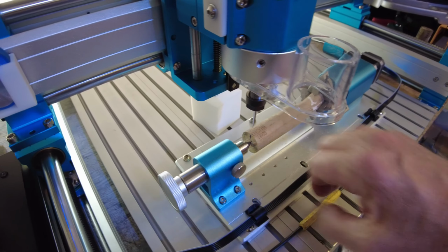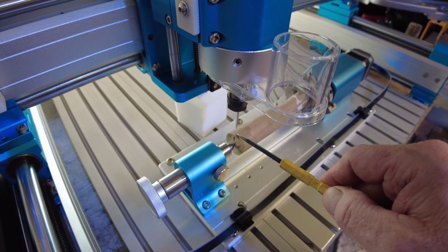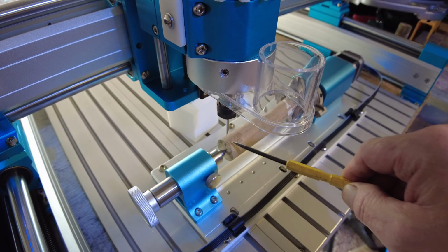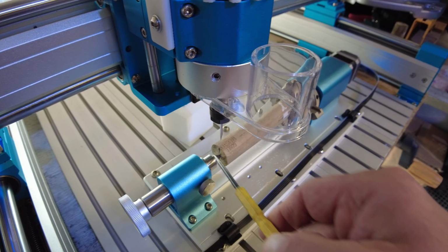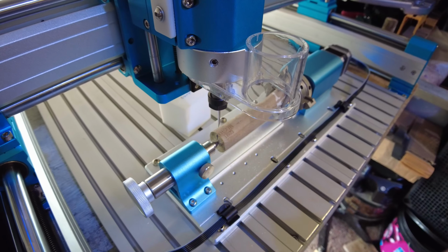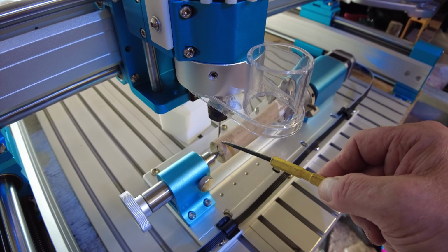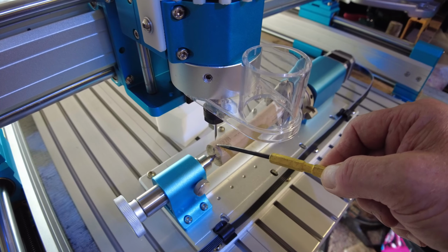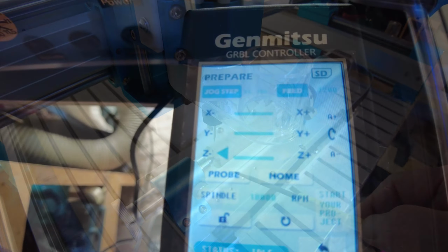Now obviously I've set it in about 5mm from the edge, roughly. But in the software program, you've got to remember that the software unwraps this. So whatever that distance is from there right the way around the circumference, you'll get that as a flat surface area within the software. In the software I have the letters, and I always work from the centre. I have a centre line on that drawing, and so the letter will be put central over that.